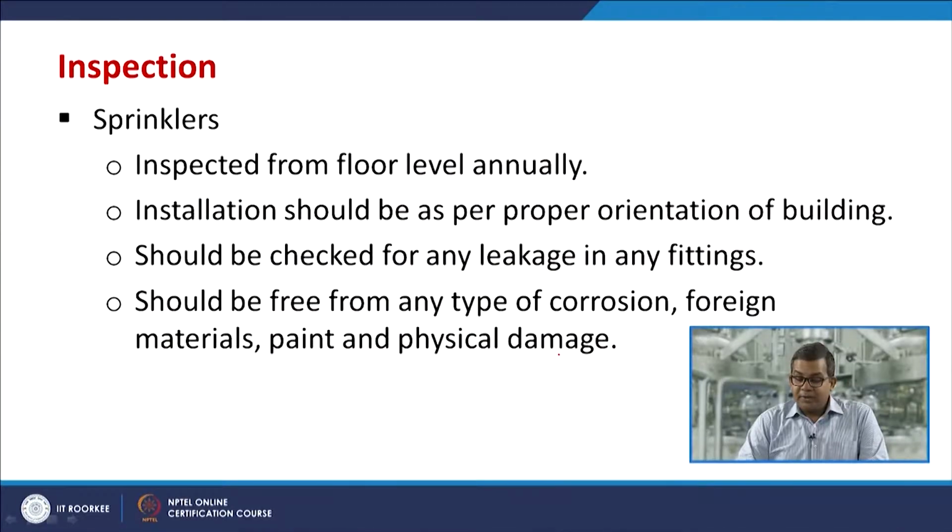As far as the sprinklers are concerned, they must be inspected from floor level annually, but it is not necessary that you perform this exercise annually, sometimes six-monthly, quarterly, etc. That is purely based on the requirement. Installation should be as per the proper orientation of the building, that is a mandatory requirement, because sometimes you may forget some dead zones where a vapor cloud explosion or unconfined vapor logging may occur. They should be checked for any leakage in any fitting, that is mandatory.